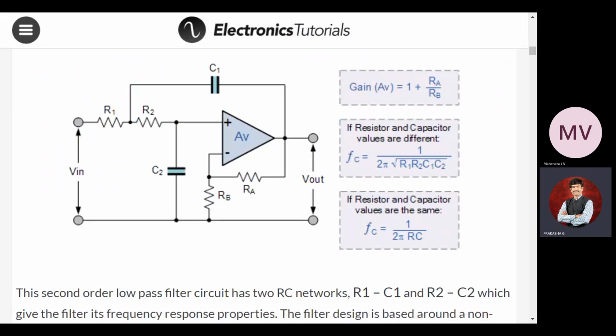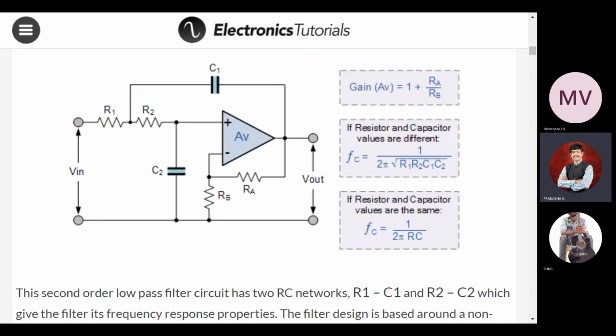Previous to that one, I need to have one more resistor. And before R2, I need one more capacitor which is not directly grounded; it has been given to the output over there. We have R1 and RF, which is connected to the non-inverting terminal. One is connected to the inverting terminal, grounded, and the other one is the feedback resistor.